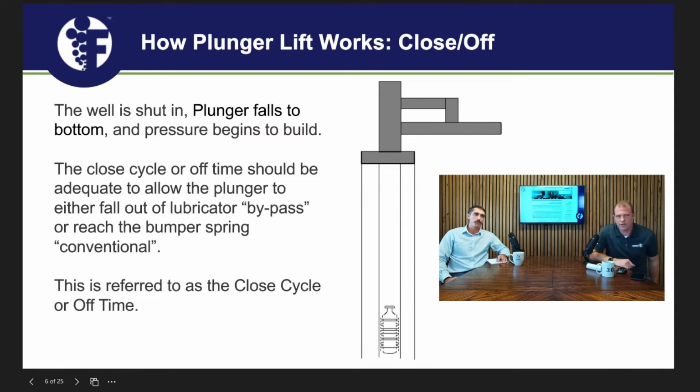So really now that we've talked about the basics of the plunger, we'll get into a lot more detail, but I want to talk about the cycles and the importance of the cycles. Because in my head, the way I look at it, if they're optimized correctly, it extends the life of the plunger, meaning that we're not wearing it out too fast. Hopefully it improves the production of the well, and allows us to get feedback on the health of the system. Is that right? Yeah. And helps prevent breaking equipment at the surface, your lubricator equipment, or even your bumper.